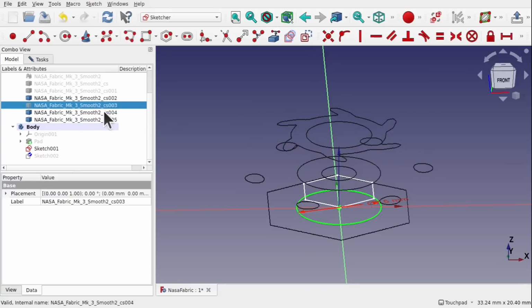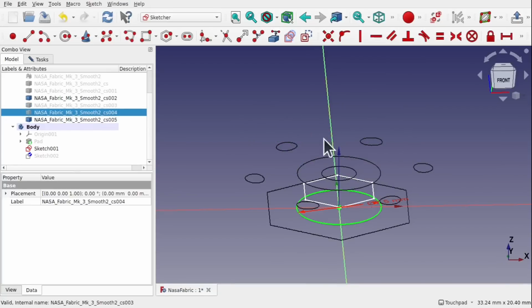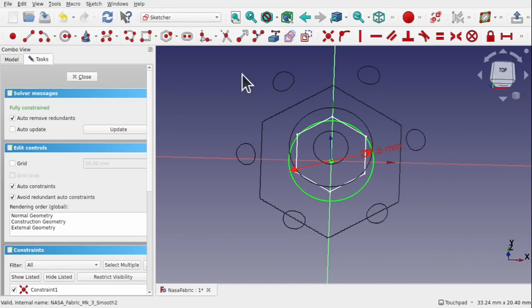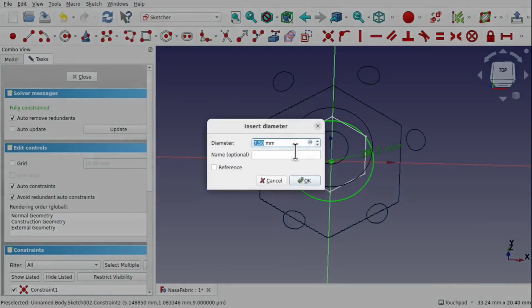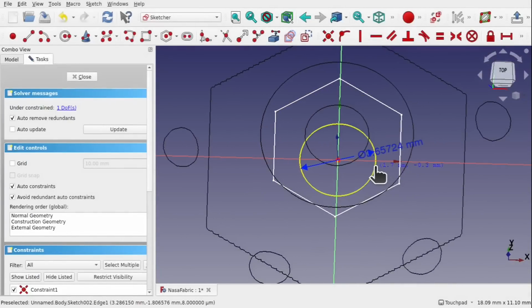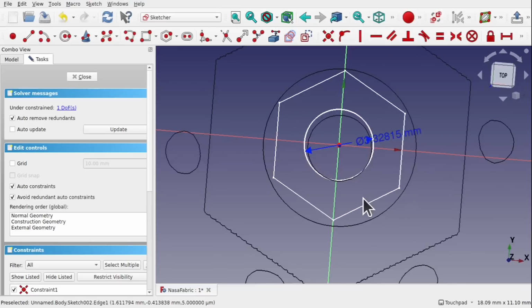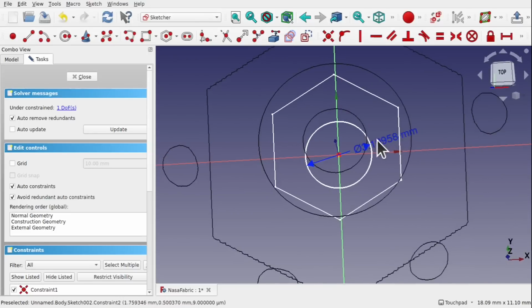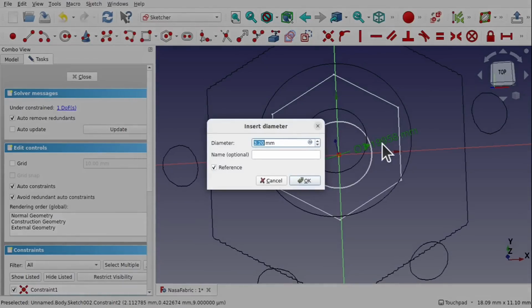Let's just hide those, clicking on them and pressing the spacebar. Let's alter that sketch. We've still got sketch open. Let's double click on the diameter, no need to get rid of that, and click on reference and hit OK. So now this is reference geometry. This means when I close this down, so we're shrinking it right down, and we can go right down and decide basically on the diameter of this. Right, so I know it's 3. I can come back in, set diameter to 3, reference automatically goes off, hit OK.